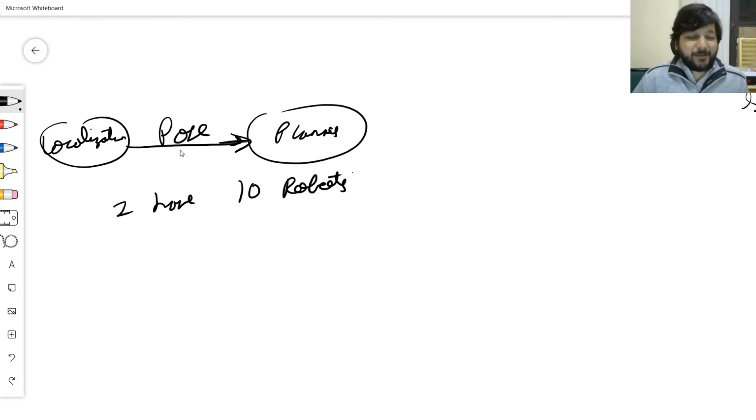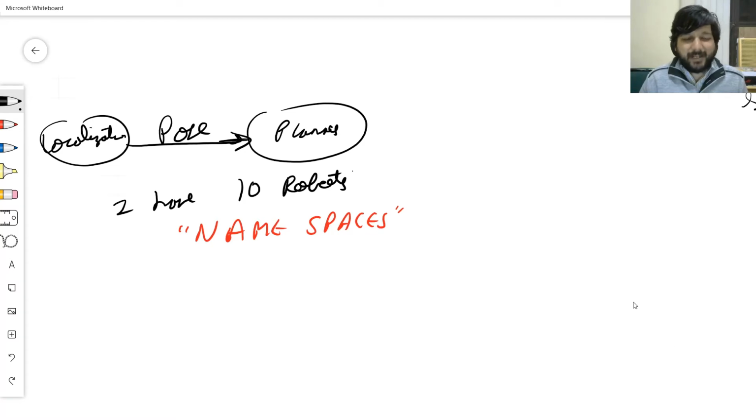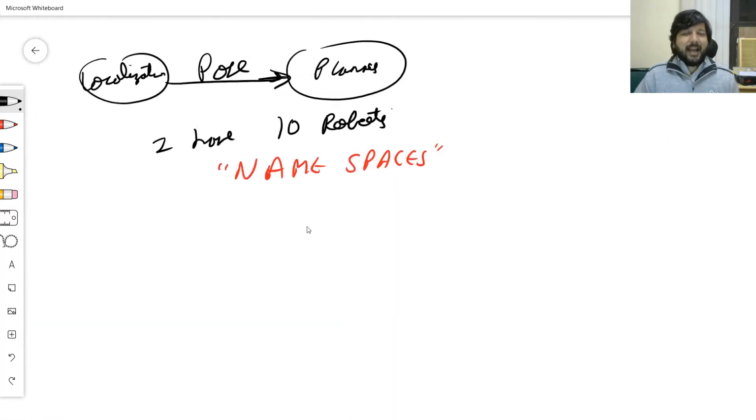That's a problem that has already been seen in software, where different functions could have different names, and the answer is, of course, what are called namespaces. Now, I'm not looking at namespaces in the programs, because ultimately ROS programs are also Python or C++, so those namespaces obviously hold. I'm looking at the namespaces of the communication mechanism, which is basically these topics.